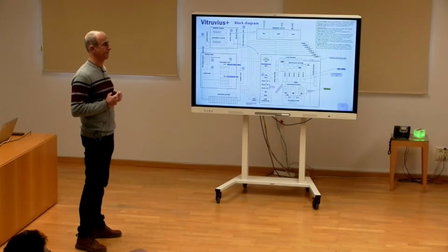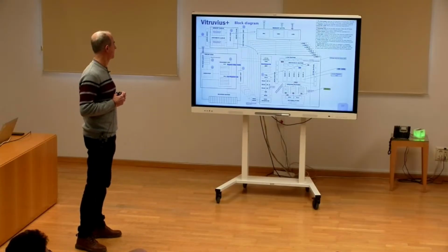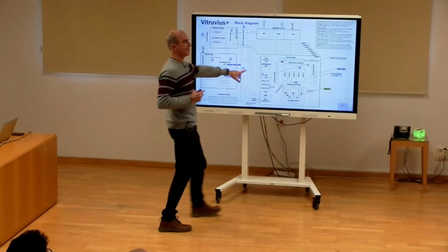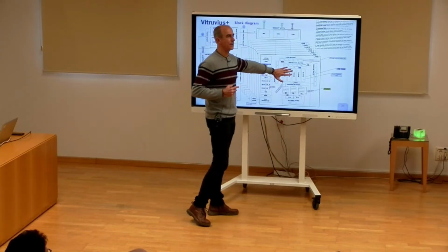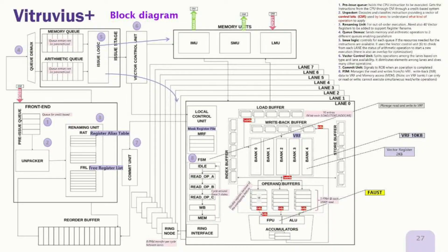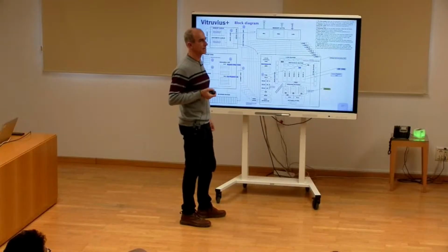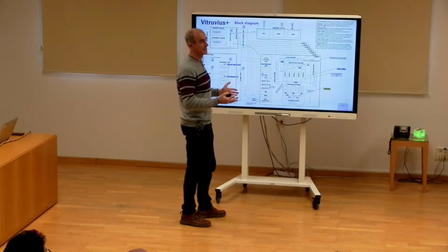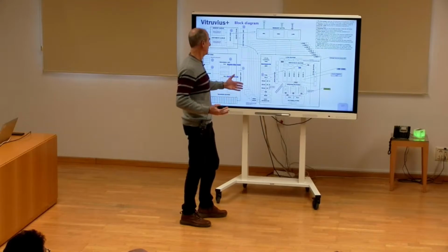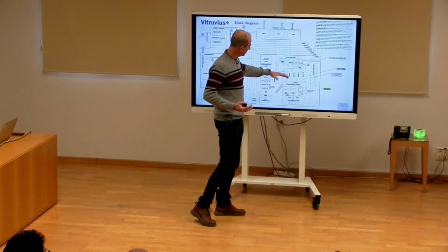So then in the picture, those banks are register files? This one? No, these are the RAMs which contain the vector registers. So it's a RAM inside the vector unit. It is a RAM, but they're used like a register file. Yes. It's because of the size. You can compact the size, and because you have a very modular structure.